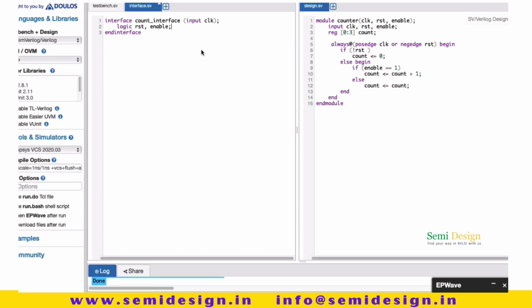The clocking block is used for sampling the input and output signals, over the positive edge, before the positive edge, or after the positive edge of the clock. It samples the signals before the positive edge commences, so that inputs are prepared before the positive edge has arrived. These are the kinds of information which can be declared or defined in the interface. Also, an interface can have constants, variables, parameters, functions, tasks, and many other things.